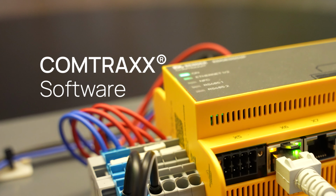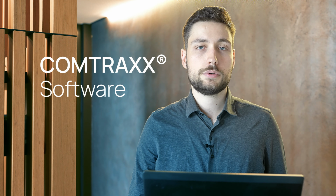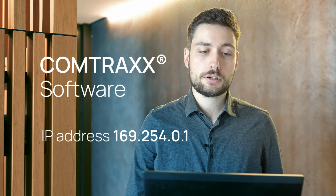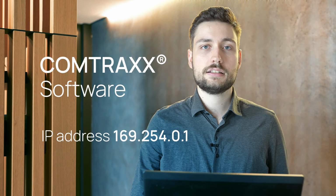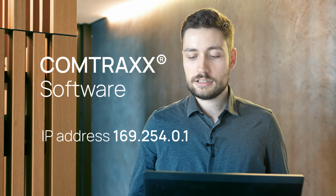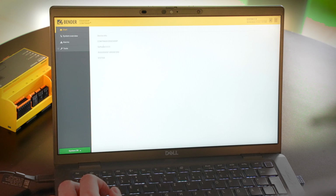Here I have an EDGE500IP directly connected via cable with my laptop. So to get to the web interface and to open up the COMTRAXX software, we need to enter this IP address here, 169.254.0.1, and go straight to it. And then we will go to this landing page here, where we see some information about the device.